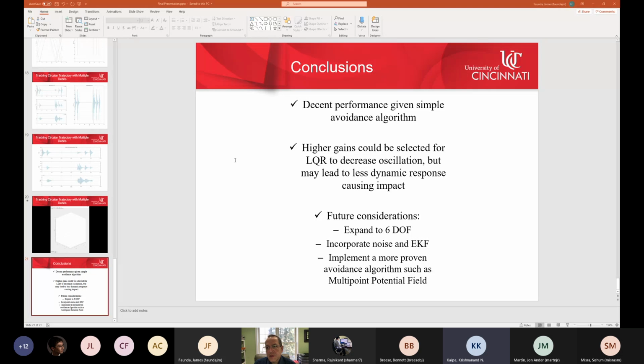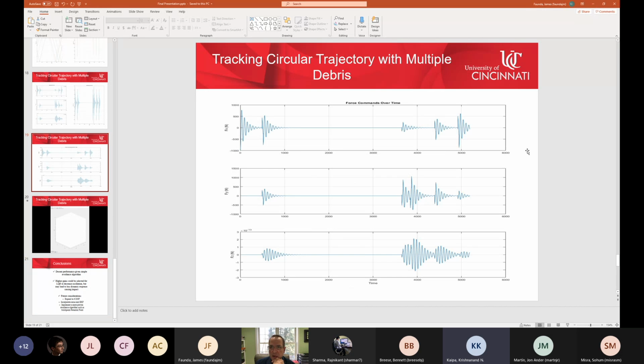Quick question. The oscillation that we're seeing in the trajectory, I believe I saw some oscillation in the applied force. That implies that we're firing thrusters in the plus X, plus Y direction. What's driving the natural frequency of that oscillation? Have you looked at different tracking filters that allow a smoother thruster burn, so you'd have one kick to adjust one of your orbital elements, and then another kick to recircularize your orbit?